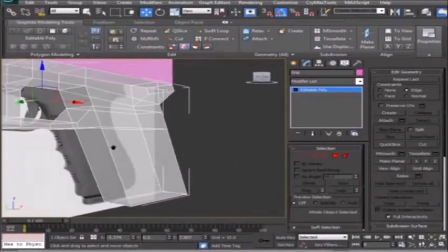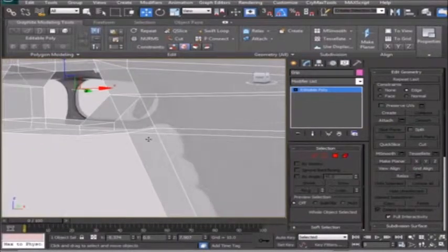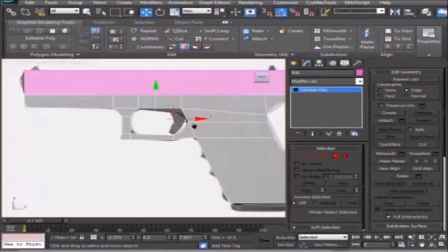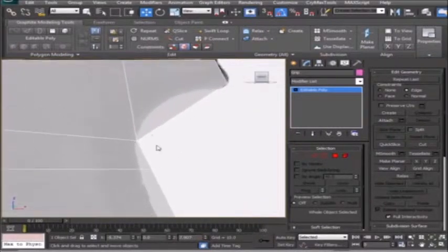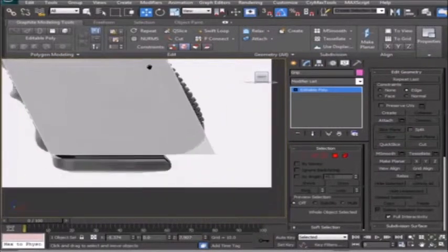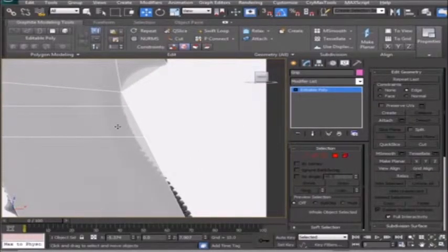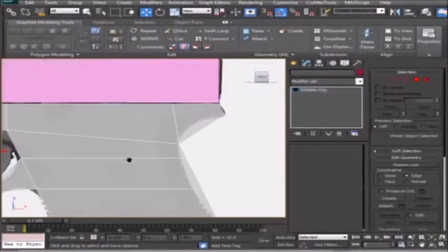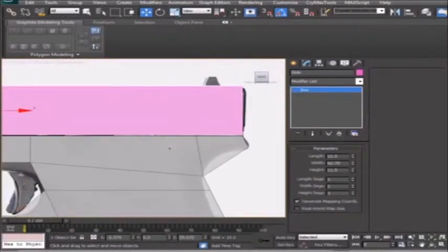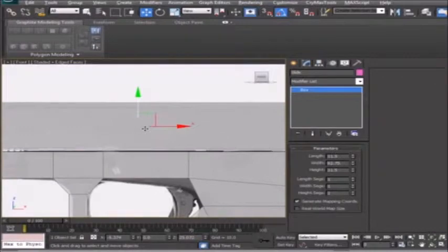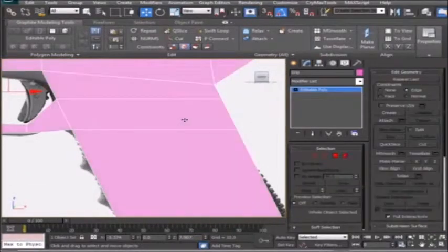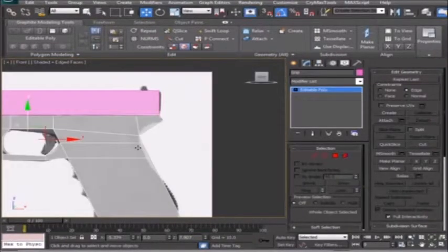It's transparent now. And I can pick up what's going on in the back, which can be very helpful when you're going to actually try to line some of this stuff up. And you can still pick off of it. It stays transparent. I hit Alt X on this one, do the same thing. Alt X again will toggle it back and forth. Okay, so I'm going to keep it transparent.